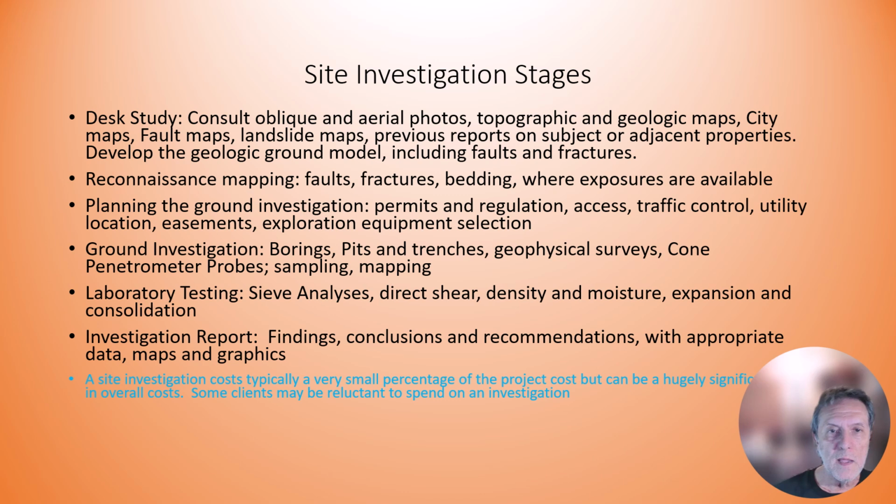First try at the project site is to do reconnaissance mapping. So we look for faults, fractures, bedding. If we found any in the desk study, we got to look for those things where exposure is available. Then we can go ahead and plan the ground investigation. Are permits required? In San Diego County, you need boring permits for any borings that are deeper than 20 feet or will encounter groundwater.